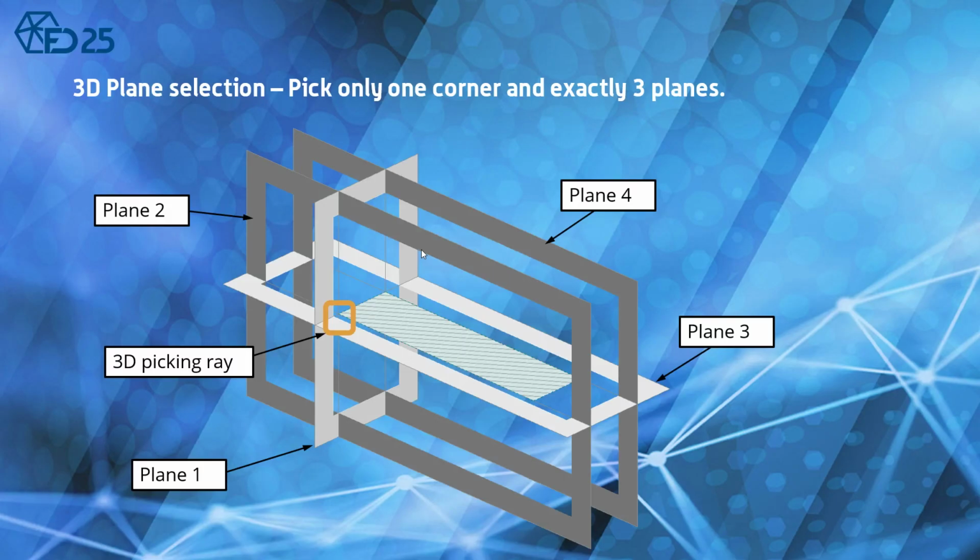So there's a question: every custom section should be parametric, because when we do a section in the section editor, it won't do design check. Actually, the new version of FEM-Design will allow design of any sections, even if you draw it yourself. But if it's something really crazy that the automatic shape recognition doesn't work, then it doesn't. But if you draw an angle, then it can do it perfectly. Or if you draw an I-beam in the section editor yourself, then it works. So it doesn't have to be parametric to make it work. You can also draw it yourself in the section editor and still it works.